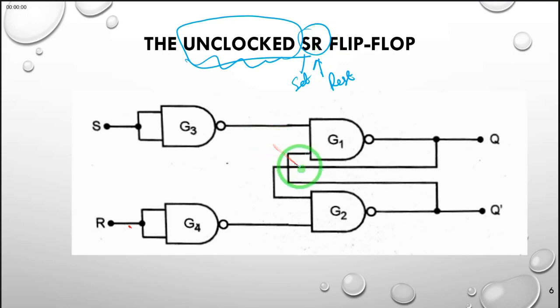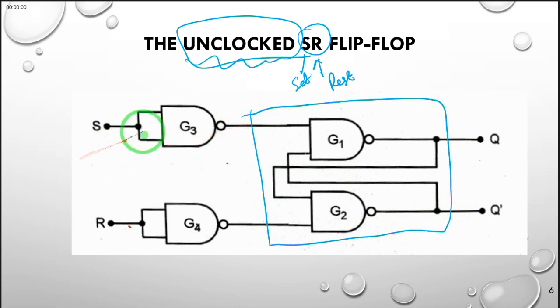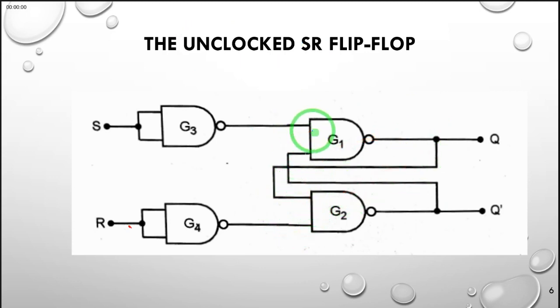So we are just modifying what we consider to be the latch. Instead of shorting our gate 1 and gate 2, remember it was shorted and therefore this was getting us 1 input, instead of now shorting the inputs of our 2 gates G1 and G2, if we feed that gate with an inverted version of S input and R input, then we are going to get that flip-flop that will have the characteristic of set and reset states.